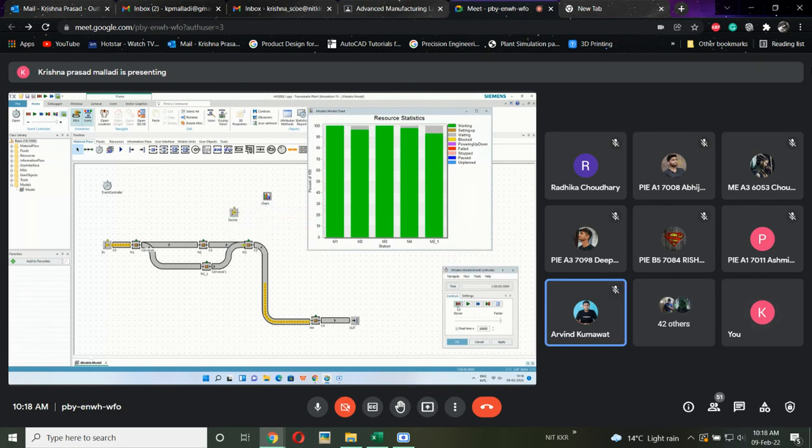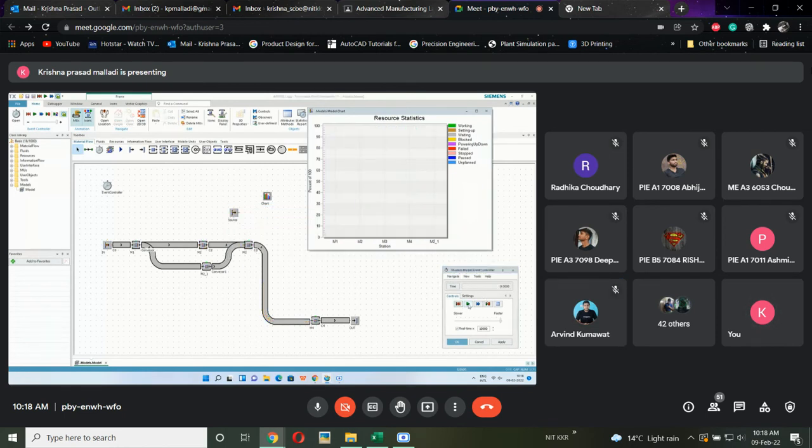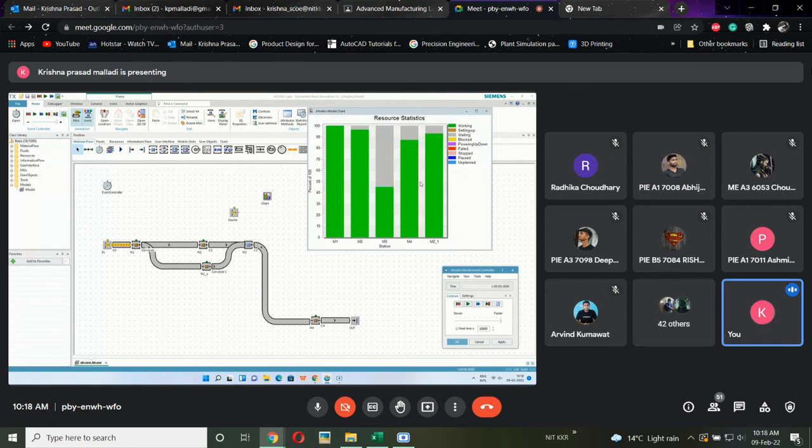See, this is what exactly M3, the initial model, is. Now M3 is utilized up to 45%. We cannot increase beyond this. 45 is the maximum. Why? Because we can't decrease the processing time here, and at the same time we can't increase the number of machines anymore. So M3 is constrained to 45 percent only. We will be achieving at most 45% in this process at M3.